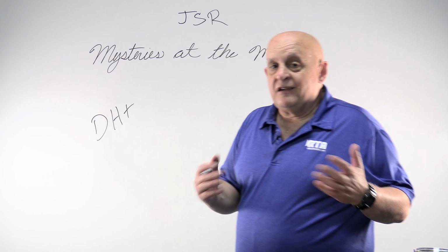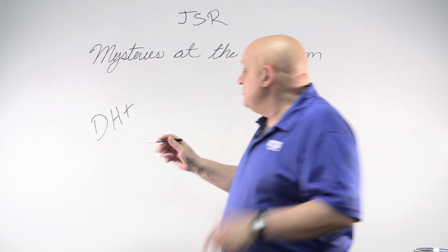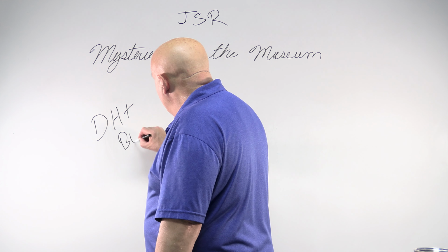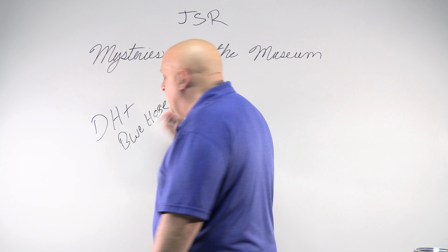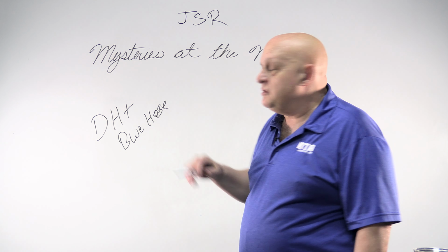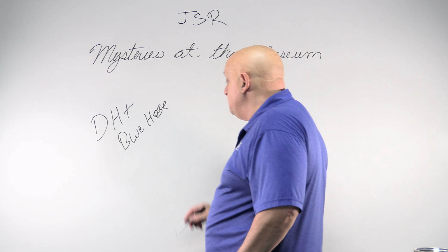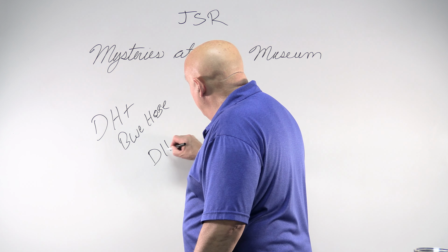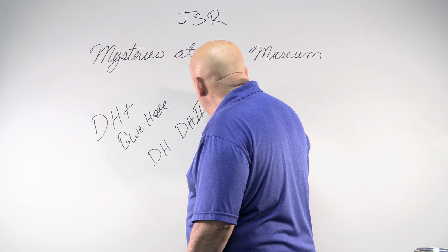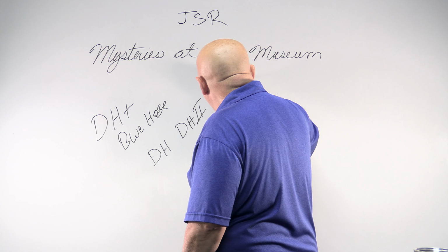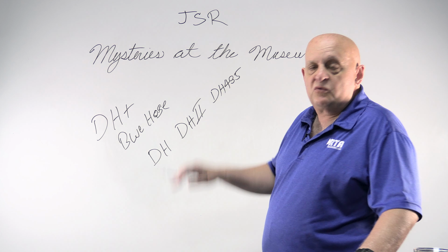When somebody says I have data highway, well, this is generally the blue hose. If you walk through an old plant and you see a bunch of blue cabling, that's the blue hose. That means it was DH+. But there were actually 4 different kinds: there's data highway, there's DH+, DH2, and there's DH485. Different kinds of Allen Bradley PLCs use different ones of these.